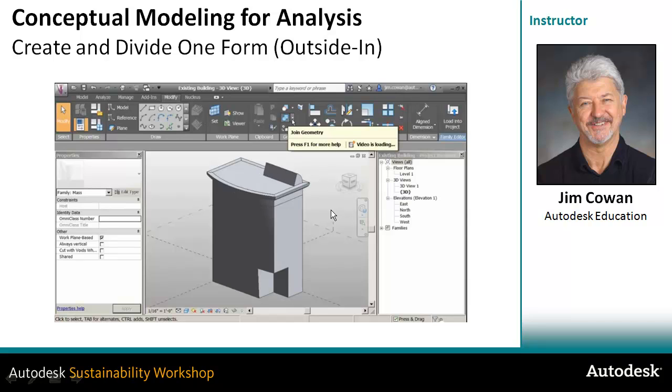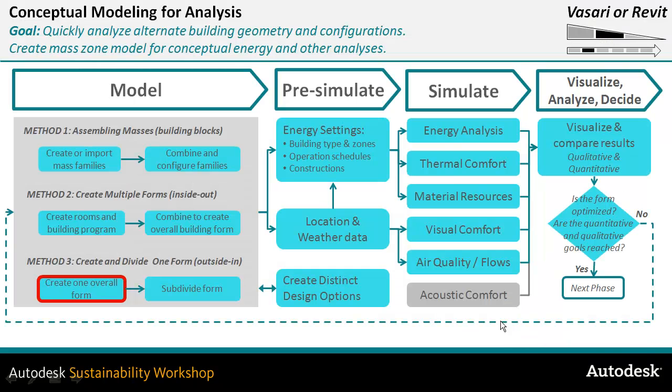But you know that you're not actually going to analyse that building, because if you analysed it, you're actually going to assign to, say, the different surfaces of that roof things like percentage glass. So really what you're doing in this scenario is that you're thinking about existing buildings that will provide the context, and it's appropriate to model them just from the outside in, as it were. So in that scenario, you're just creating an overall form because it's important for the energy study, not because it's the building being analysed, but because it's a building creating context.